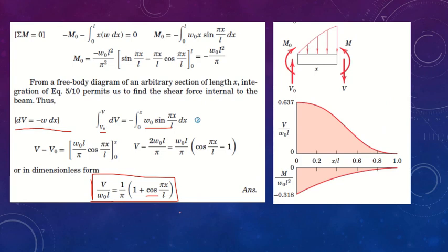The shear forces are reducing, but correspondingly the moment is increasing. At 0 you have a negative moment, and as it goes away from the joint of the cantilever, the moment increases gradually. Now we are going to talk about another example where you have to find or derive an equation. We have multiple types of equations for load distribution.